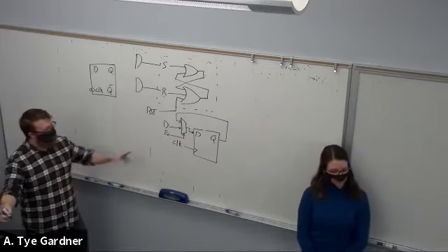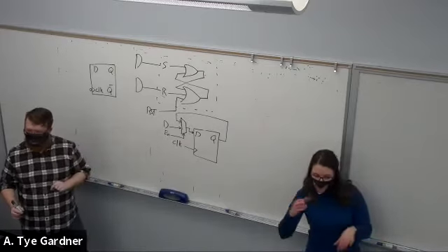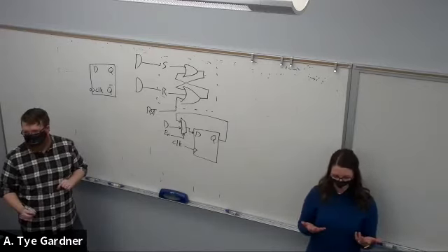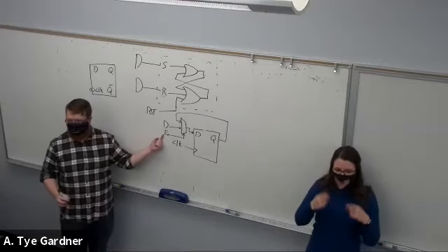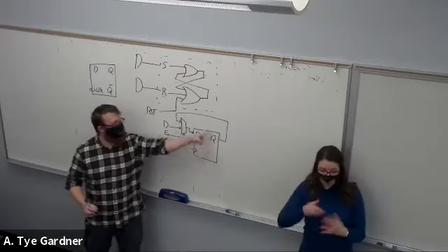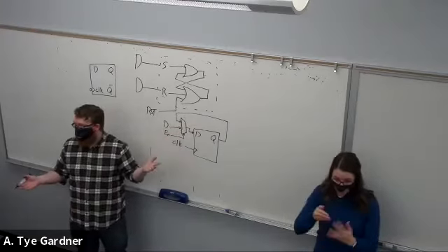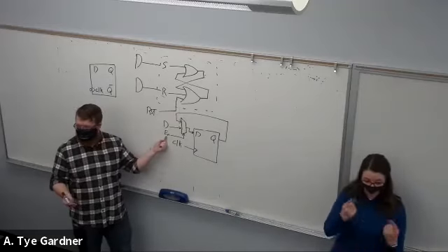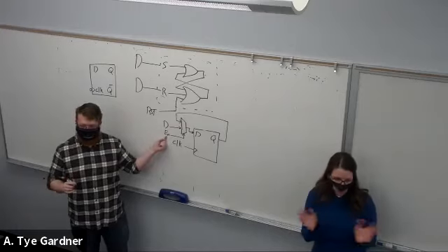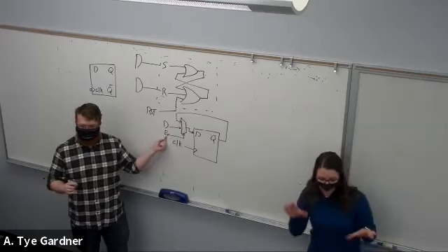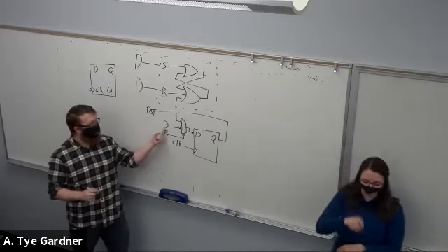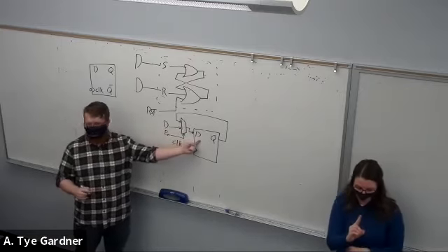Now, is this an active high or active low enable? Think about what happens when enable is 0. It sends Q back through, correct? Meaning if the clock happens and enable is 0, nothing changes. So is that active high or active low? It'd be active high, wouldn't it? Yes, active high enable, because I need enable to be 1 in order for D to pass through into the flip-flop.